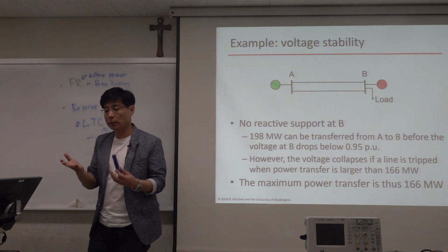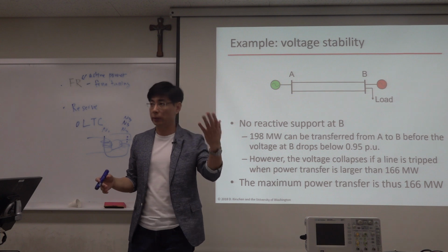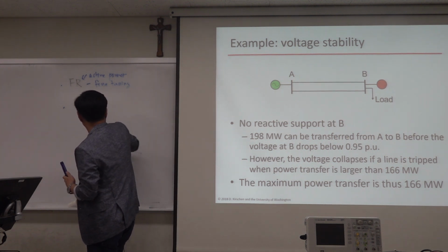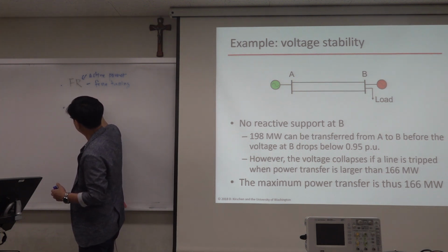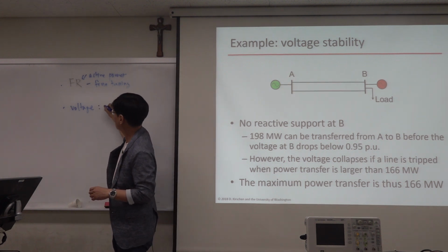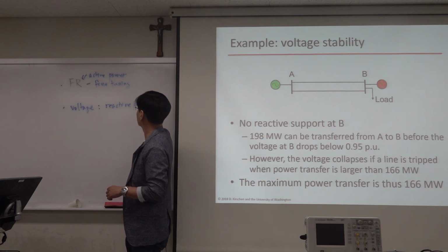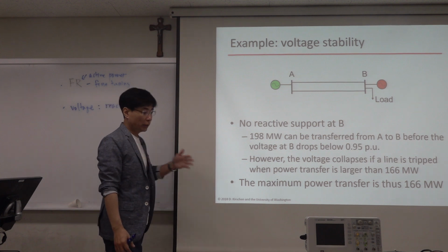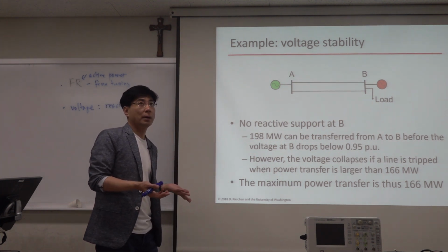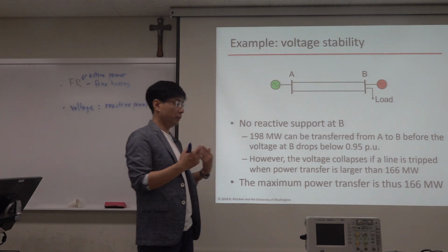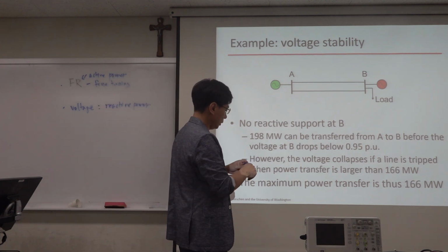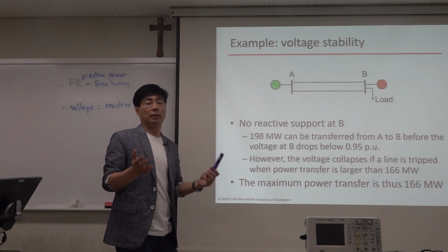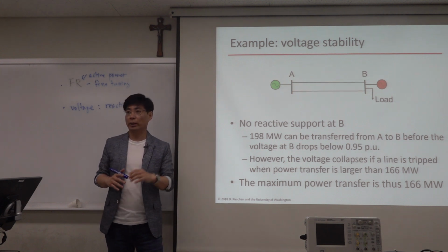We don't need it. So the frequency is associated with the balance of active power, the generation and total loads. Okay, right? But another part is the frequency is an important one, but another important one is voltage. Okay, and this voltage is related with reactive power. And so you will see voltage is controlled by injecting or absorbing reactive power. Injection of reactive power is by using capacitance. Okay, and absorbing of the reactive power can be done by a coil, or a generator can provide reactive power or absorb reactive power. And that kind of things can happen by changing the phase between current and voltage.